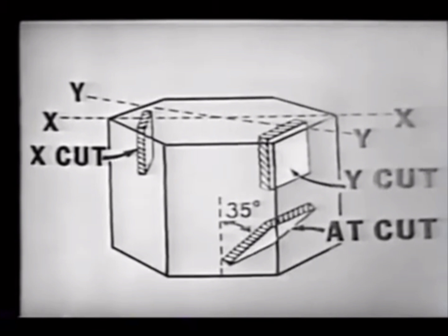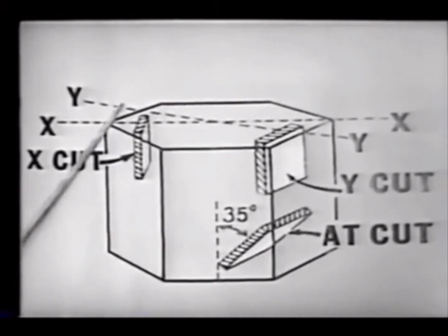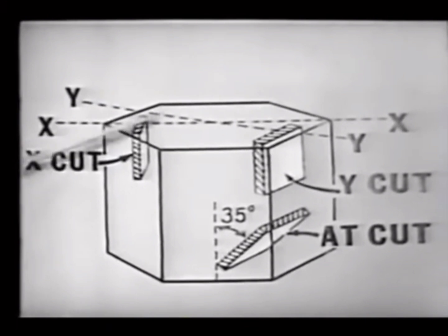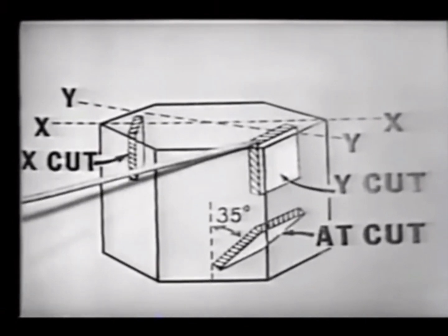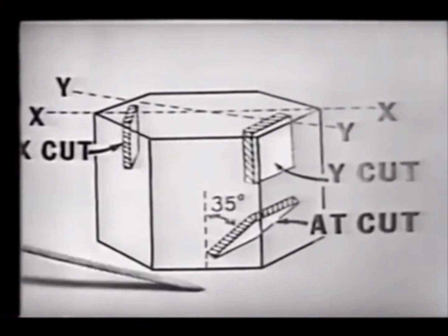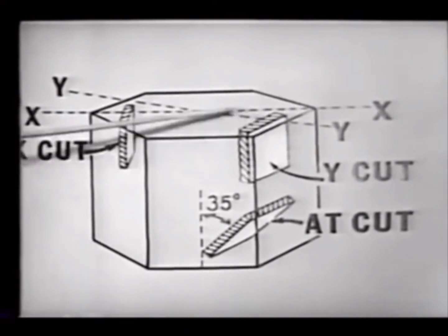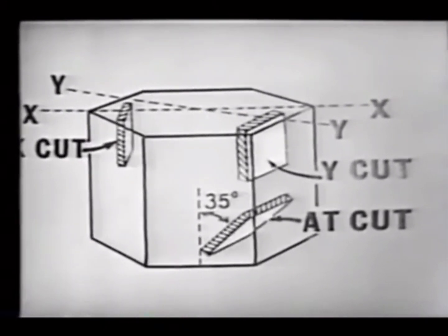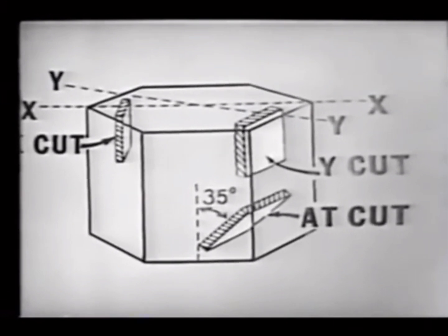For this cut, we will use the y-axis, which passed through the face of the crystal. This cut will be taken perpendicular to the y-axis, and it also is parallel to the z, which you will recall ran through the center of the crystal. Remember, perpendicular to the y, parallel to the z. And again, to get a more realistic view of this cut, let's go back to the mock-up.